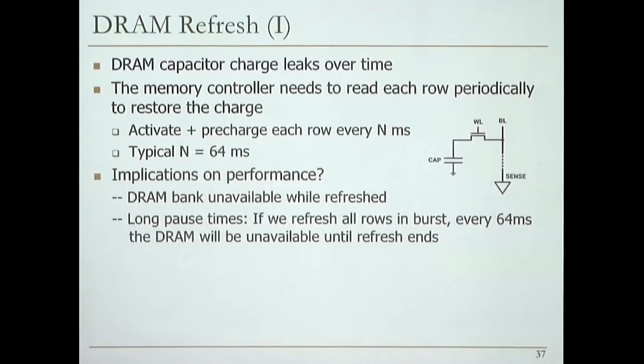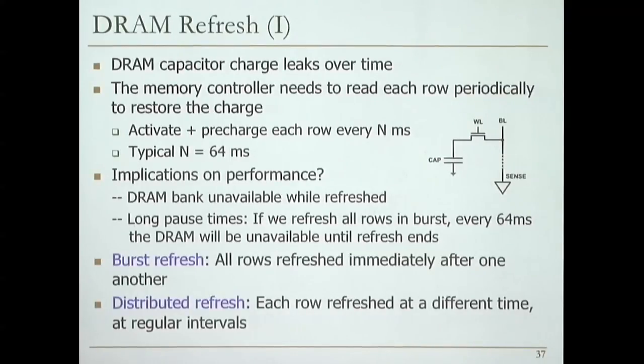And there's also an issue, long pause times. If you refresh all rows in a burst at the same time, every 64 milliseconds, that's the refresh interval in today's systems. Actually, it's reduced to 32 milliseconds, I think, in LPDDR4. Is that correct, Hassan? Yes. OK, there you go. So if you refresh all rows in a burst every 64 milliseconds or every 32 milliseconds, the DRAM will be unavailable until refresh ends. Now, this makes no sense, of course, right? So this is called burst refresh. All rows are refreshed immediately, one after another.